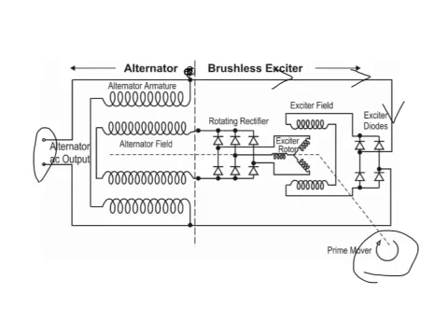If you look back over here, these same 2 points are essentially the 2 points all the way across to the alternator output, meaning we have an AC current flowing. Now, we come in with AC current to this full wave bridge rectifier right here, and of course its job is to convert AC to DC. So we get a rectified DC, and DC current now flows out to the exciter field.